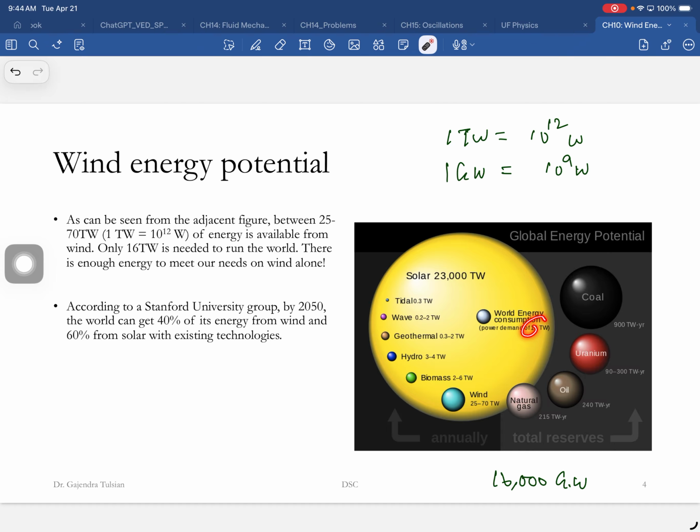Now here's the deal. As the blades are rotating, the air here becomes turbulent, and you don't want this blade to go into the turbulence. Then it can't extract energy. You want the blades to be rotating in clean winds. Okay. So that's where the tip speed ratio comes in.